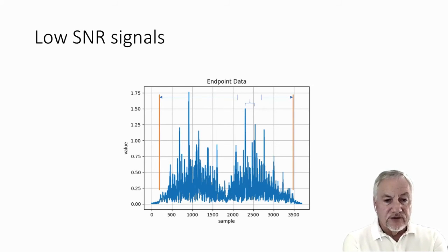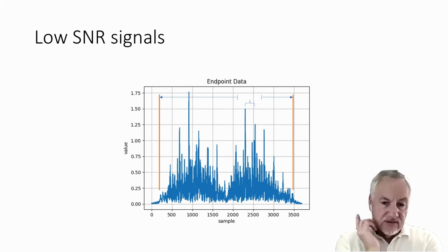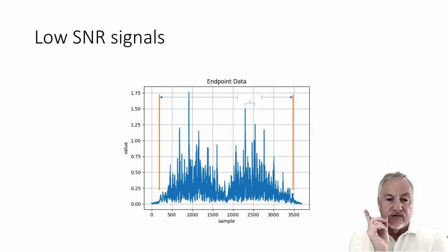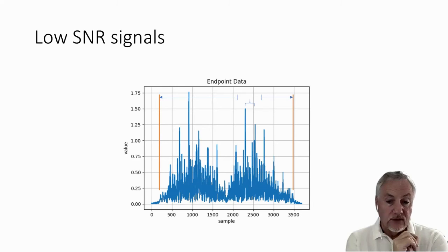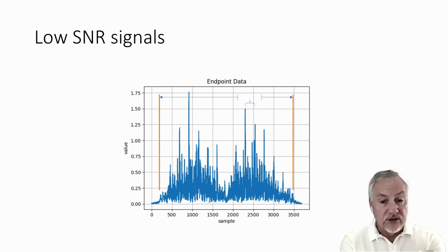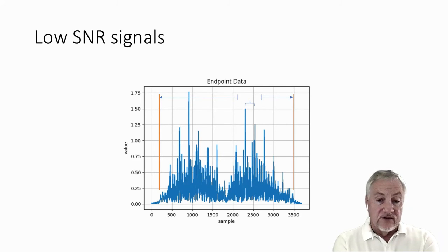Notice that this signal, I should say, the center of the signal is very close to 0. That's due to the Barker code that's used in the short and long training sequences. So it's something that we have to be concerned with, because we don't want to just capture half of the main lobe. We'd really like the full main lobe.